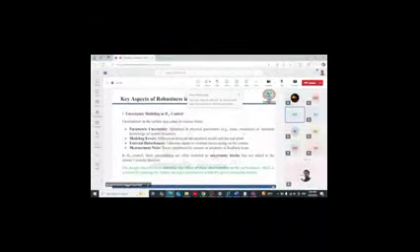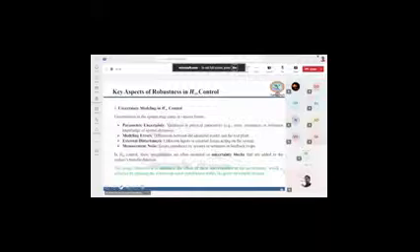Uncertainties. So what are the types of uncertainties? Maybe parametric uncertainties, modeling errors, external disturbance, or measurement noise. So in H infinity control, these uncertainties are represented by blocks that can be added in the system's transfer function. The main objective of H infinity control is to minimize the effect of these uncertainties on the system performance, which can be achieved by ensuring the system rejects disturbance within the given uncertainty bounds.